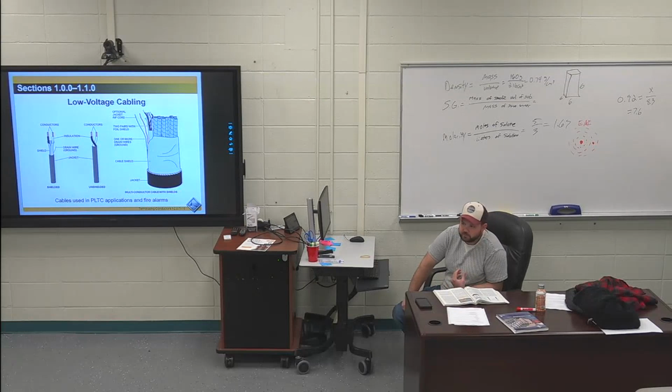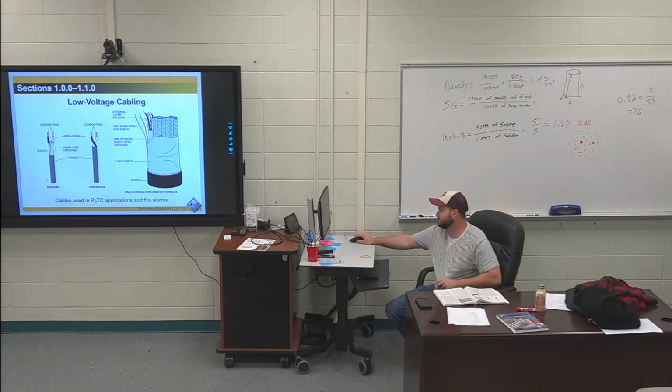Whenever I would do this in a factory, say I had this wire right here and I was running it out to a piece of instrumentation, say a pressure transducer, out in the field, I would hook that up out there, and then inside my motor control room, or wherever your control room is, I would ground on that side. I would not ground at the piece of equipment because sometimes it's hard to find a good ground out there and stuff might be moving around, but inside a control cabinet or control room, it's easier to find ground.